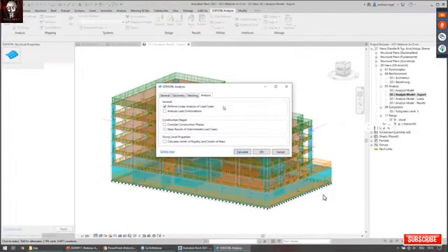And for the analysis, you can do a quick analysis directly from within Revit. So in this case, I will perform just a linear analysis of all the load cases of Revit, but it's also possible to include load combinations defined in Revit. You will see that later in this webinar. Or you can also account for construction stages defined in Revit. And now I'm just calculating this system.